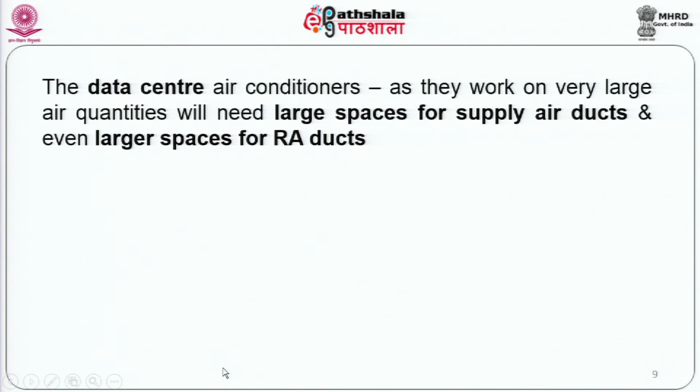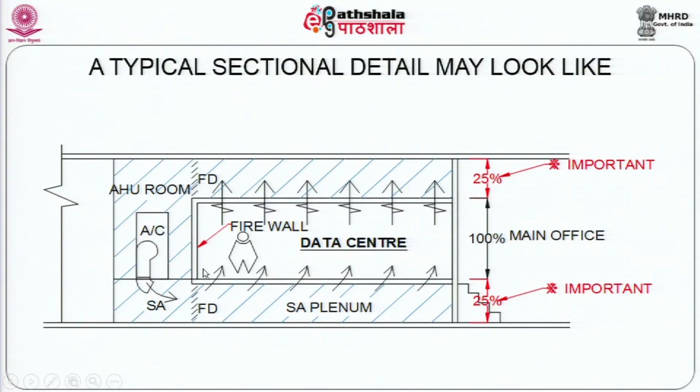The moment you put an AHU room next to your data center, what are you having? You need air conditioning to be transmitted from your AHU room into the data center, and hot air from the data center to be pulled back into the AHU room to be able to recycle that air and reuse it, so that you effect economy in the cooling load. Now, this is what it would look like. In other words, if the data center in floor plan, this is a sectional view, you would have this much as the data center, you need this much as your AHU room.